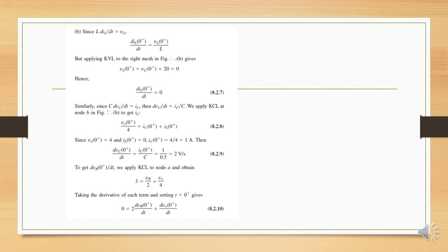Now the part B of our circuit. In part B, we have to find out L di over dt, the derivatives. So L di over dt is equal to VL, as we already know that. So dIL over dt is equal to VL of 0 positive over L, the value of given L. After again applying KVL, we got dIL over dt at 0 positive is equal to 0.